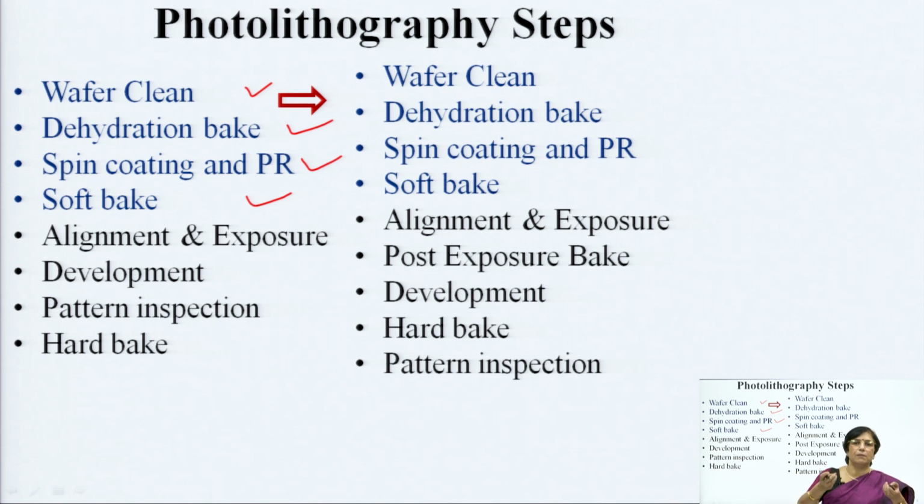It is properly lying on the surface, covering the entire surface, and the binding property is precise enough that no scratch or extra pressure can remove any part of the surface. So you have to ensure there is proper adhesiveness to the wafer surface, and for that reason you carry out the soft bake.